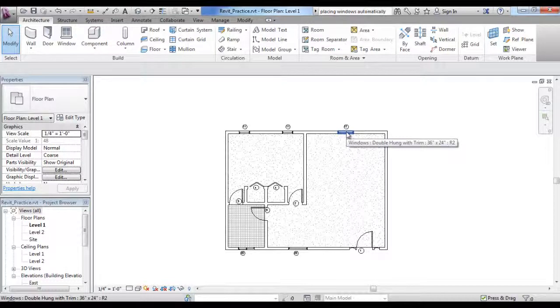But the most important thing from our perspective is that the bottom sill of the window needs to be higher than the bottom of the countertop. The countertop is 4 feet. If we add a 4-inch backsplash coming up the wall, made of the countertop material, which is relatively standard, then you need a 4-foot sill height because you're going to have a 2-inch trim, so you need that 4-inch height. Okay, so